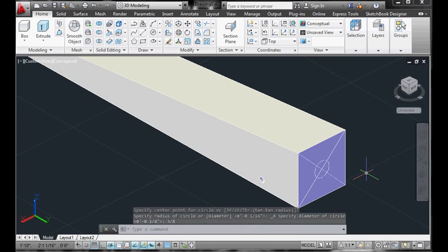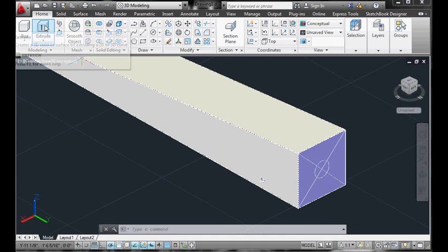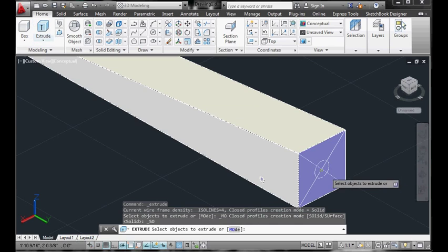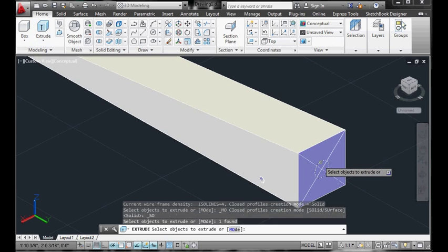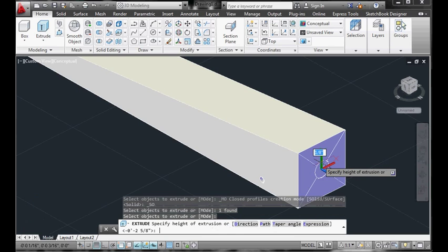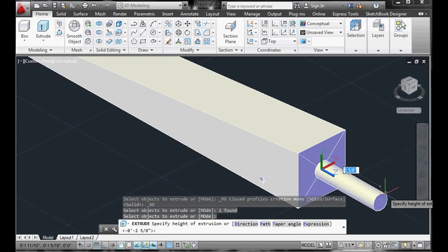Now, we need to do the exact same 2 steps we did before of extruding and solid subtract. However, in this one, we cannot just extrude to an endless area. We need to go a certain depth in. So again, click on extrude, click on the circle you want to extrude, make sure it's highlighted, hit enter, and as you notice, it will go to the right.